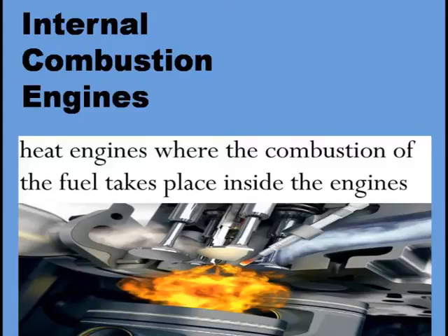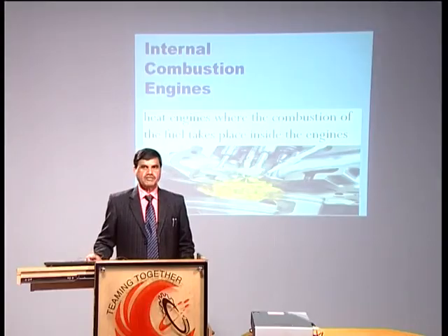Just after compression, some intense source of ignition is being provided. That intense source of ignition results in combustion. It is in the form of flame, it is visible. That flame is propagating inside the cylinder, capturing the air and fuel mixture which is available in every corner of the cylinder, and temperature and pressure inside the cylinder become quite high. That high temperature and pressure is forcing this piston in the downward direction.